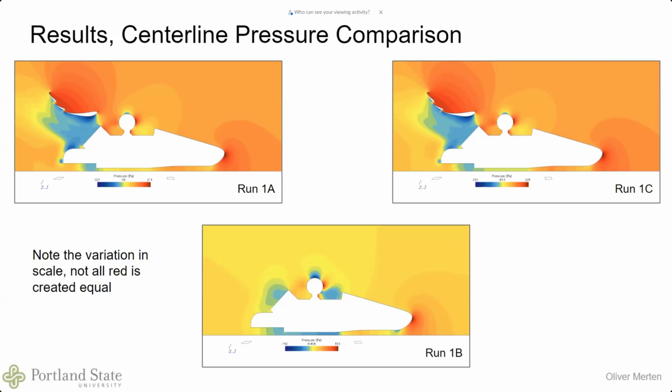And so exactly as you'd expect, there's a huge low pressure zone underneath the rear wing, which is generating the downforce, which we expect. So it's just an upside down airplane wing. Instead of creating lift, it creates downforce. And the same thing for the underbody. It has a very subtle airfoil profile to it, and that is generating some downforce, albeit much less than the rear wing.